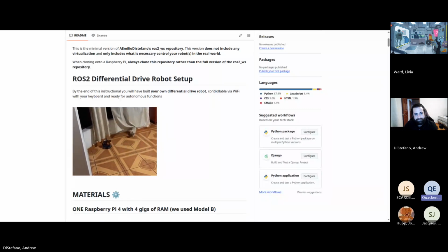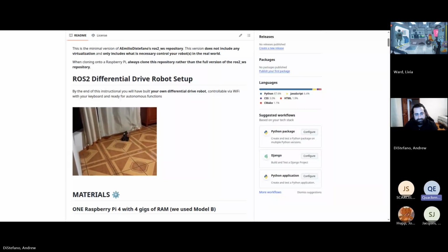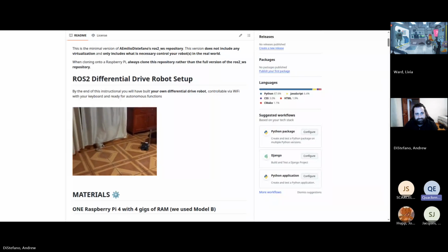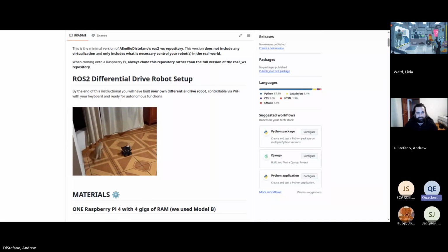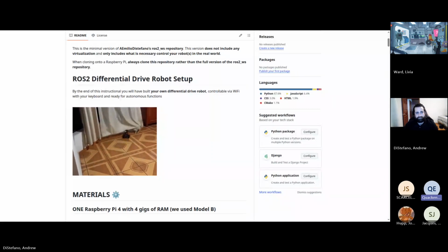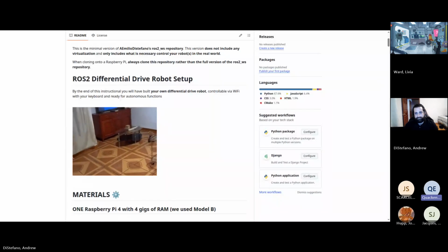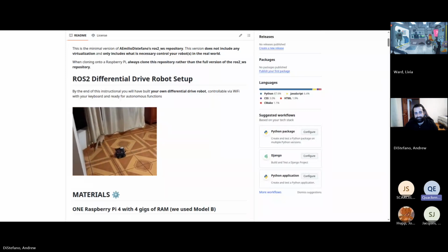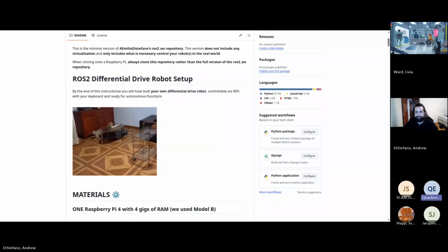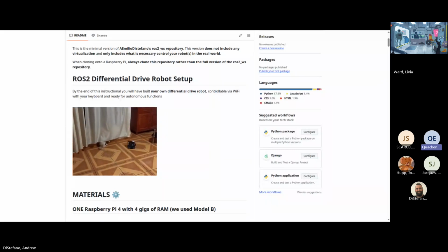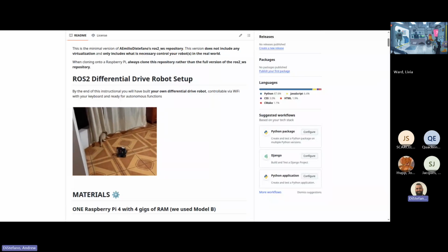But LoRa also has a lot of goodies in its bag to pierce through the noise floor. The way the LoRa modulation works is that it uses a chirp, and the idea with a chirp is that you're using the frequency shift, your frequency versus time slope, to encode the data. So you can actually recover signals that are below the noise floor. And LoRa has adaptive data rates. If you go down to SF12, that will send smaller bits of data, but also boost the transmit and do more error correcting, so you can cut through the noise floor very efficiently. That's pretty fascinating, man.